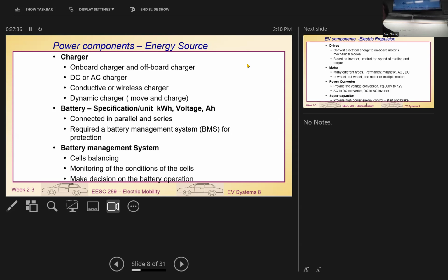Even though it is a little bit different, that could be a critical issue we look into. Maybe when the battery is new, the deviation may not be too much. But after a few years, even a 10% deviation would be a big disaster. Say 3.7 volt is the standard. Adding 10% makes 4.1 volt. Then the upper limit for the battery will be, say, 4.3 volt.